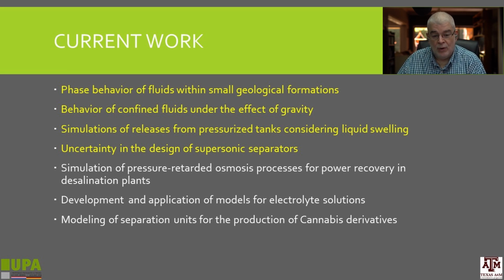We are working on liquid swelling inside these tanks and these process safety calculations. When the tank opens, there is bubble formation, and the liquid rises because it's liquid plus gas inside the phase. So this has an impact on the rates of the releases.